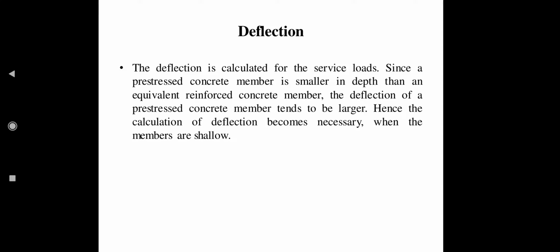Therefore, the deflection may be more in this case. So it is mandatory to determine the deflection of prestressed members when the members have very little depth, or when the members are shallow.